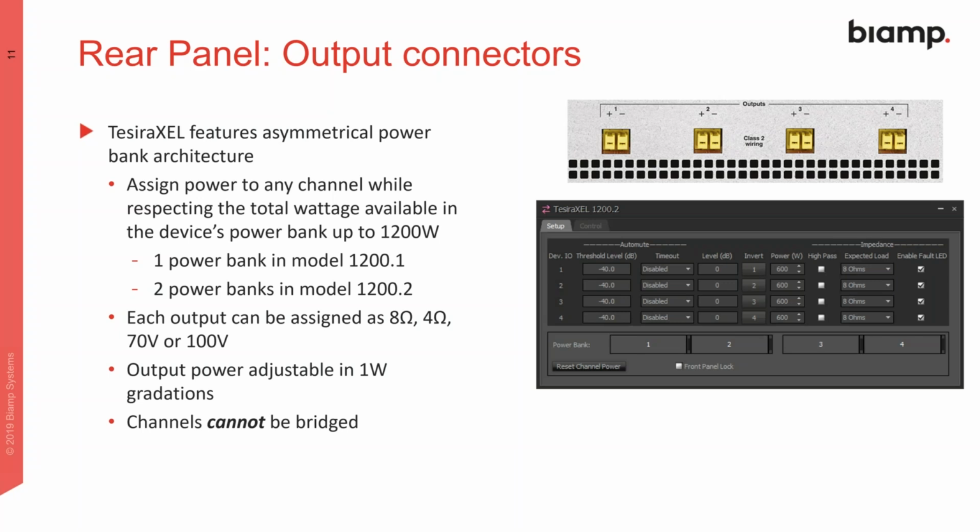The one thing we cannot do is bridge channels. So we support 8 ohm and 4 ohm operation, 70 volt and 100 volt operation. We don't go down to 2 ohms. So for that, we would need a different architecture.